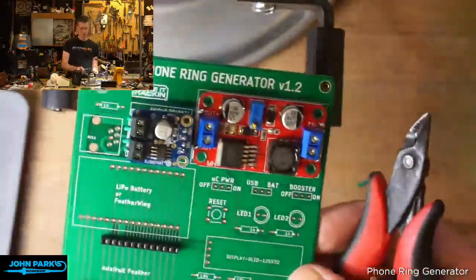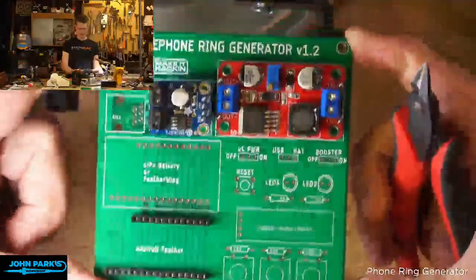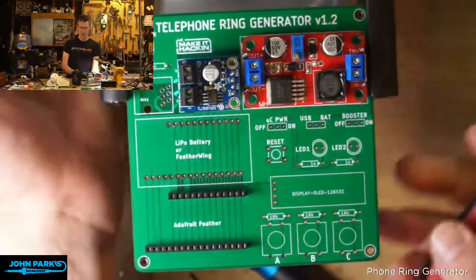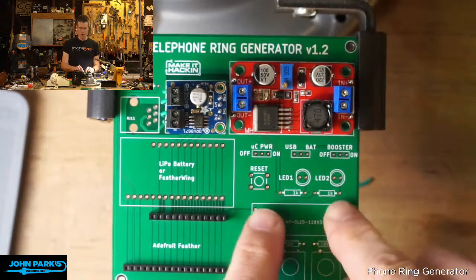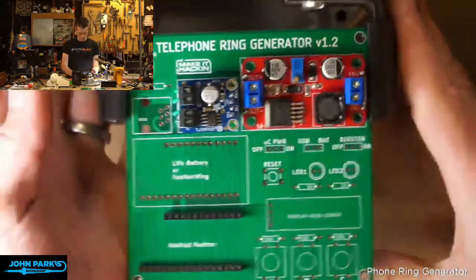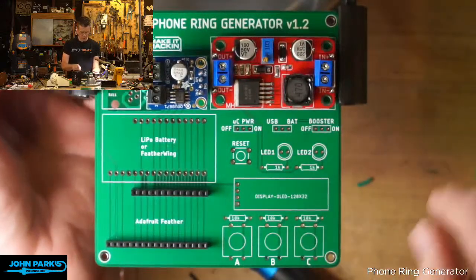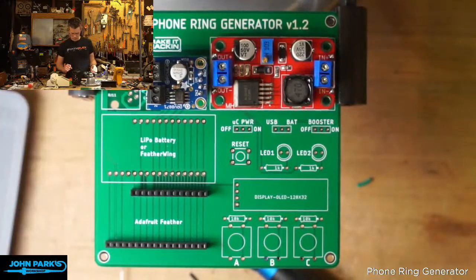Also, there are some mounting holes on here, which is great. So if you end up wanting to mount this inside of a project box or something like that, that would be terrific. All right, it's looking cool. Let's see, I can probably do smallest things from the middle on outward. So I'll do these resistors, then the buttons and switches, and then this display and these biggest buttons. You could get away with any order on these, but that's how I tend to approach it.